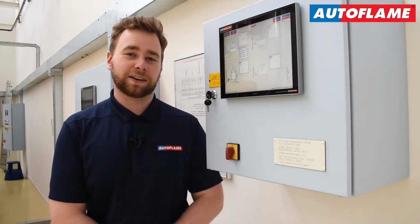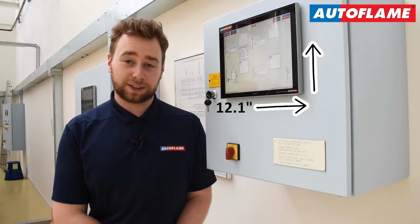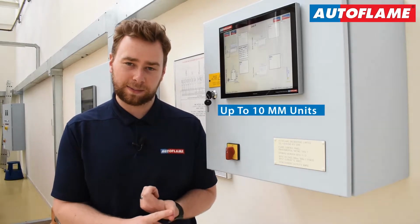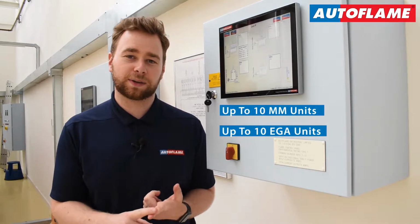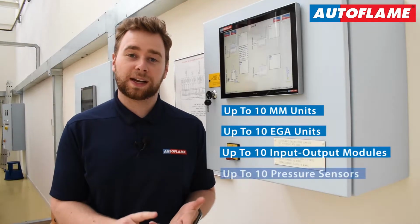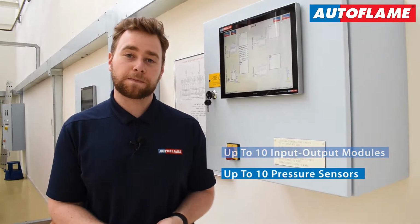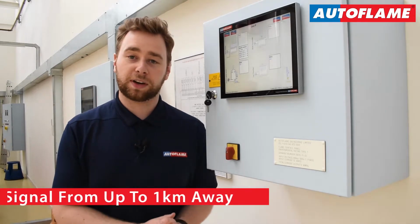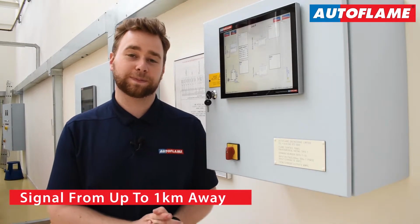The Mk8 DTI features a 12.1-inch capacitive touchscreen and acts as the communication gateway between the user and up to 10 Mk8 MMs or mini Mk8 MMs, 10 Mk8 EGA EVOs, 10 input-output modules, and 10 gas and air pressure sensors. All the information gathered by the DTI is stored for up to 3 years, can be remotely accessed by a BACnet or Modbus system via Ethernet links and RS422 up to 3,300 feet or 1 kilometer away.